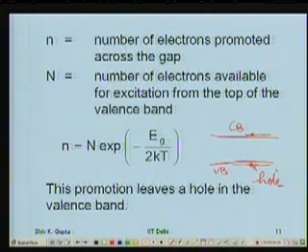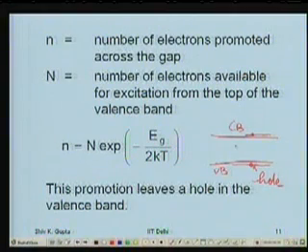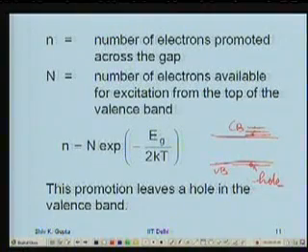And this hole can be occupied by some other electron which is lying below. It can come and occupy this. In turn the hole will go down, the energy level. While getting excited, electrons in the conduction band travel and go to the higher energy levels. When they get excited, the holes start traveling downwards, go to lower and lower energy levels. It is as if electron is a negatively charged particle, we know that, so hole is a positively charged particle, moving in the direction opposite to the electrons. And that is how we treat it.